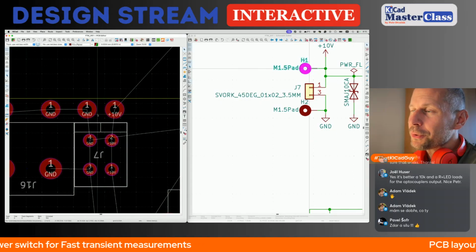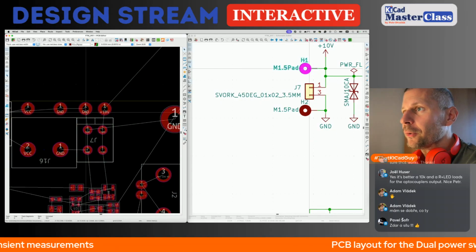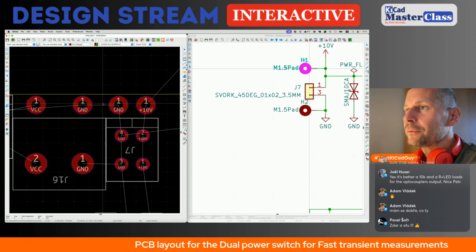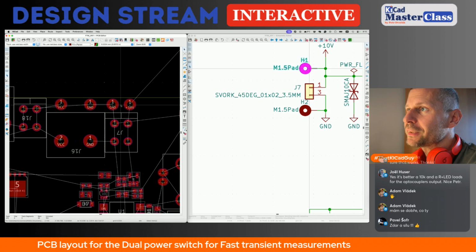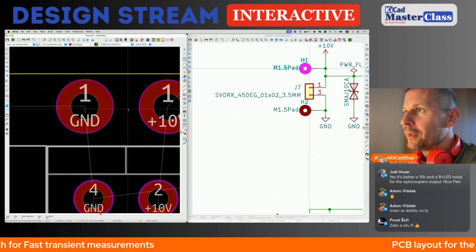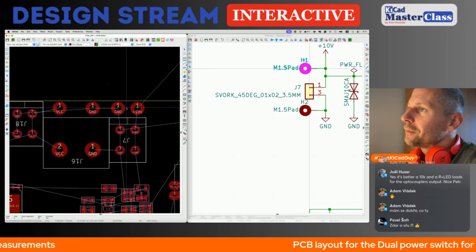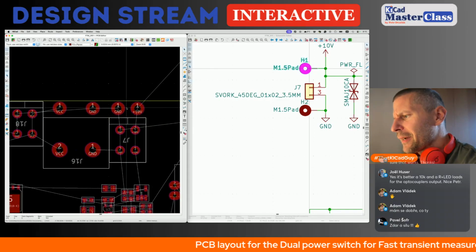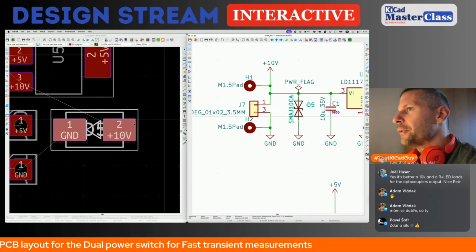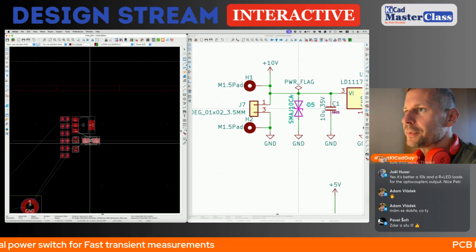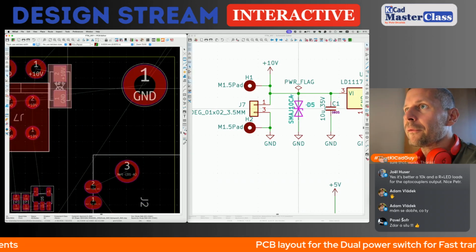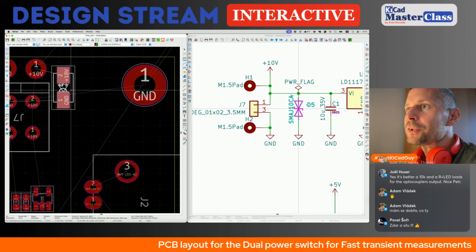I moved the mounting holes far from each other because the previous position was too close. Not because of electric safety, but because of manufacturability. The copper area will be quite narrow, not close to clearance, but I like it more this way. Now the Transil, the TVS, transient voltage suppressor.